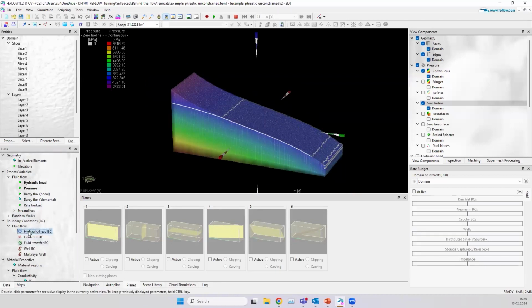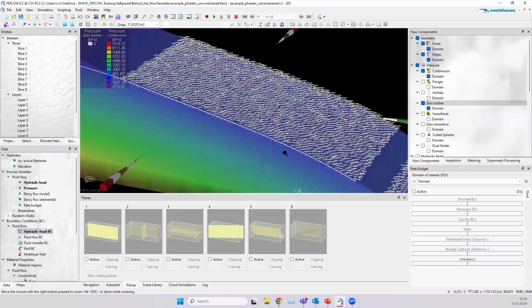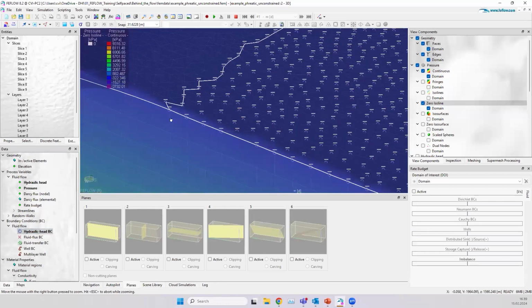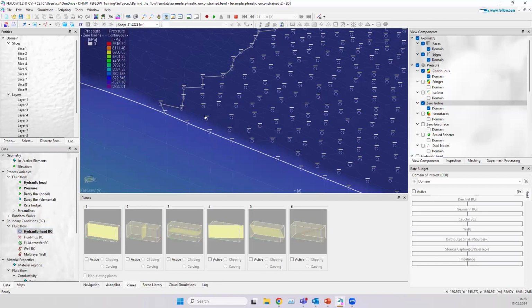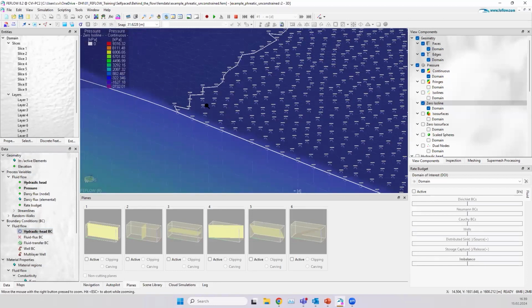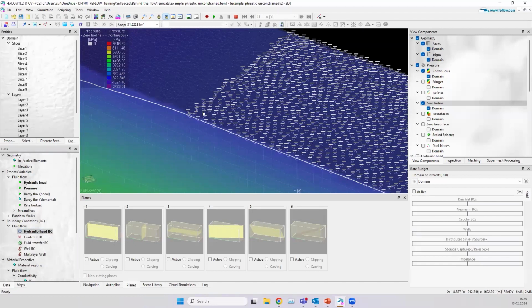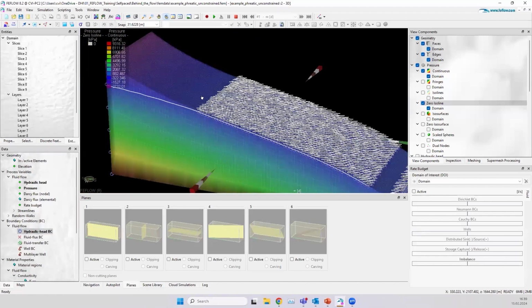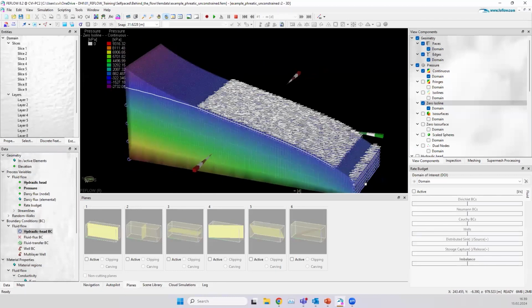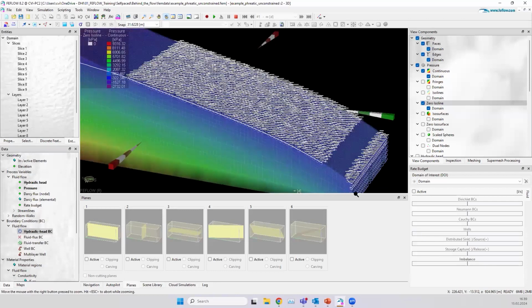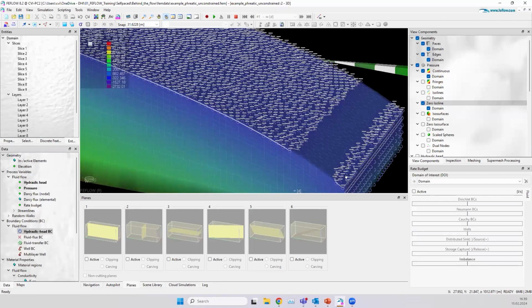If we plot the hydraulic head BC, you can see that FEFLOW has introduced automatically some boundaries here because in all of these nodes, the water table is above the elevation. So this is what I mean when you can identify these spots where the water table is rising. And then here the slope changes, and again here there is also an increase. Again the water table wants to rise above the topography, but because of the rule we basically just set the heads here.